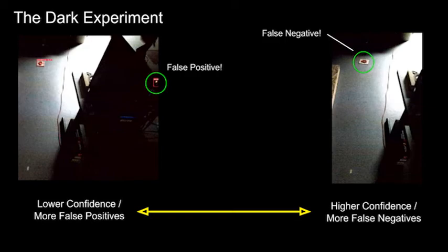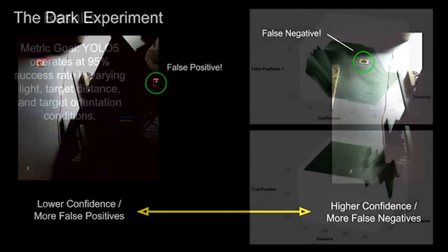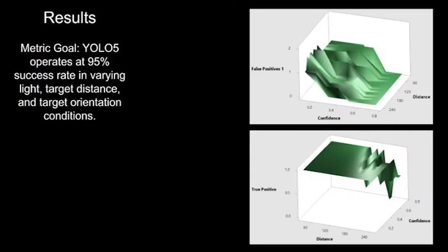Two trial sets of 176 images each were analyzed. Our goal was a 95% positive object detection rate. Observe the upper surface plot. As the YOLO confidence is lowered past 0.6, false positives occur at all distances from the camera. At confidence rates 0.6 and higher, there were 0 false positives. This would be a promising performance of the system.